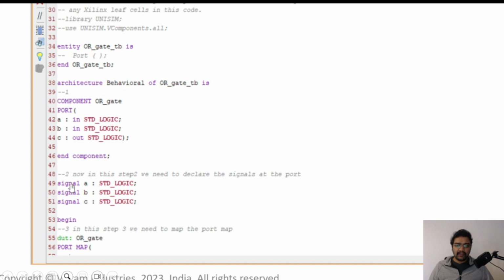So again, we need to mention the signals. This is the second step where you need to enable the signal flow through the pins. Whatever input pins, you drive the input to it and derive the output from those inputs. There should be a signal enabled. If you don't declare a signal to it, VHDL won't be understood by the FPGA or EDA tool, and they will set this port, port C, as idle, and it won't have any signal as well.